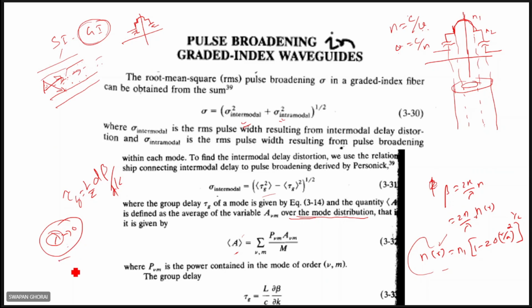That is true for multimode fiber. The multimode dimension is quite large, as I told you, it can be 50 to 100, 50 to 200 microns. So suppose the core diameter is 100 microns, then lambda is say 1 micron, or you have seen 0.8 to 1.6 microns. So with respect to 100 microns, you can neglect the finiteness of the wavelength.